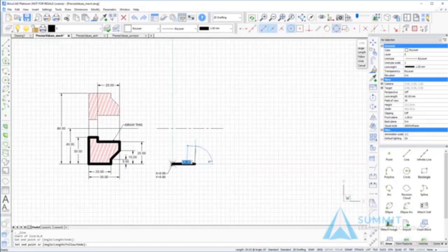The next thing I'm going to do is enter shift at 5 less than 90 and press enter. And that will create a line segment that is 5 units long and going at 90 degrees. The next step will be to enter a relative coordinate. So even though I type 10, 10, the text is prefixed indicating a relative coordinate. I press enter, the line will be drawn 10 units in the X and 10 units in the Y of where it originated.